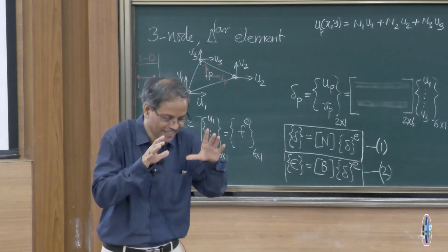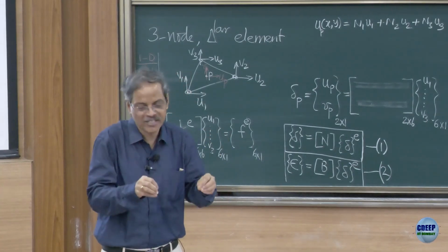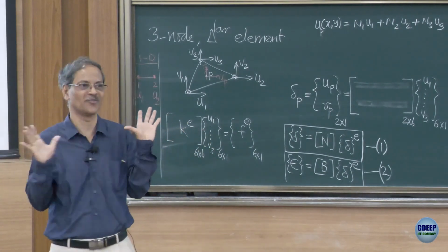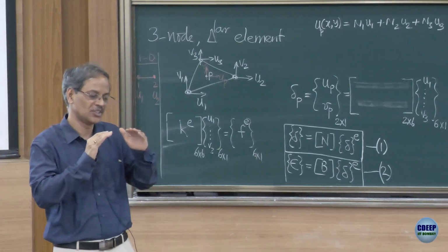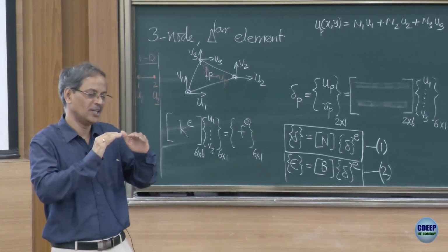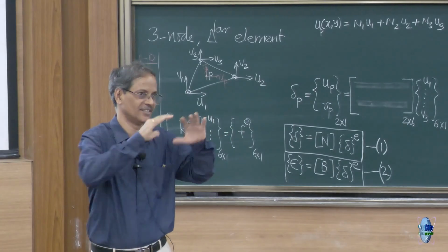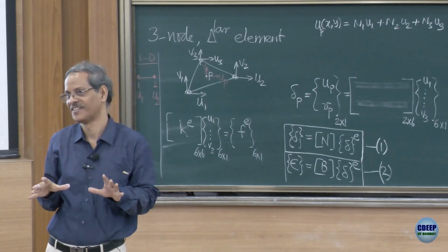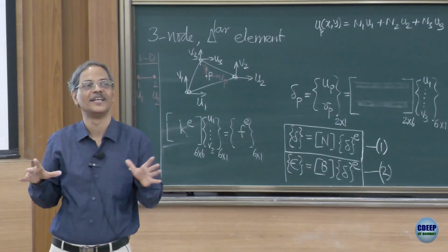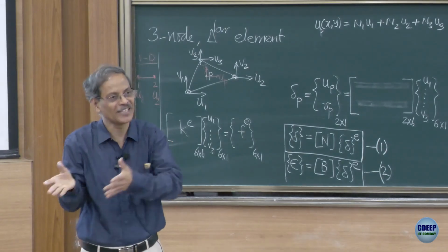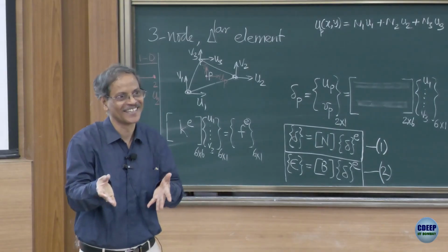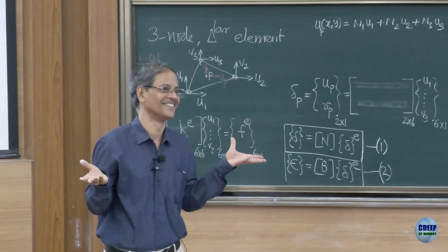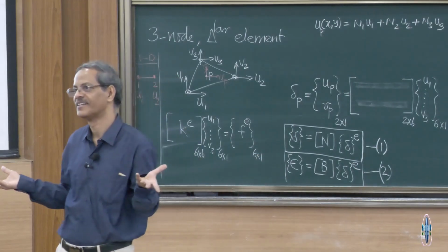It should stay within elastic zone, get stressed, deformed, but recover when the load is removed. That is the designer's philosophy. So, he or she will overestimate the loads, that is a factor of safety, and then design it. But a person who is interested in manufacturing that same car or whatever cannot manufacture it if the material does not undergo plastic deformation, cannot cause that shape, right.